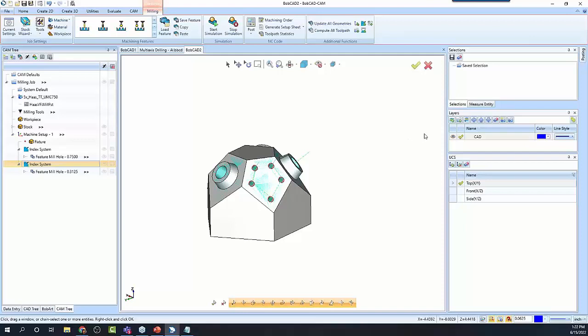All right, so the next thing that we want to do is use hole recognition. Hole recognition is a way to drill and have the software find the holes for you. It uses a knowledge base, and it can be customized so you can build some logic into it. So like all automation tools, it's about understanding what it does and how to best use it.